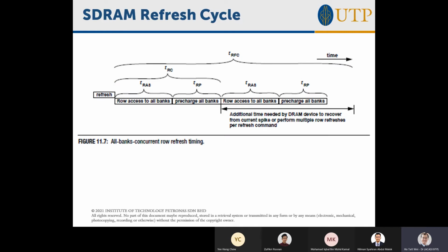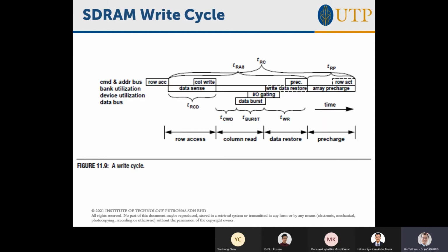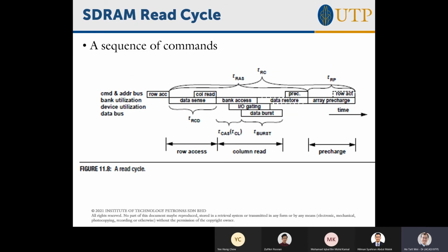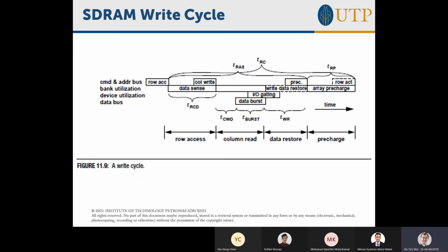Maybe if you already don't have time, I can throw it out of the assignment. I don't grade you on that, no penalty. But I want you to at least achieve being able to design and program a circuit and demonstrate it. You can read a data word from the SDRAM, and you can write a data word to the SDRAM. It is a real chip on an FPGA, and you are designing the FPGA part to talk to the SDRAM given its concepts.